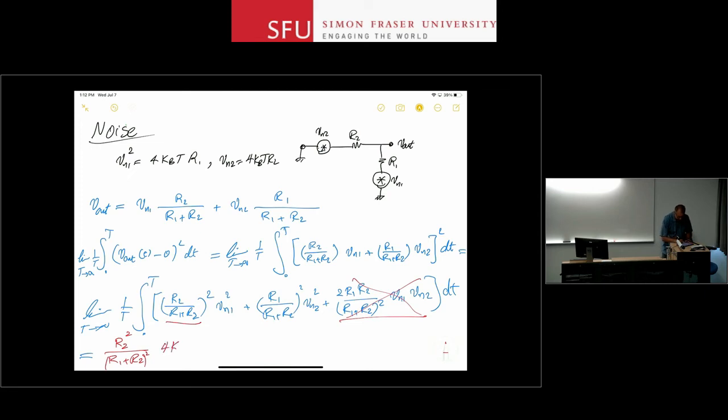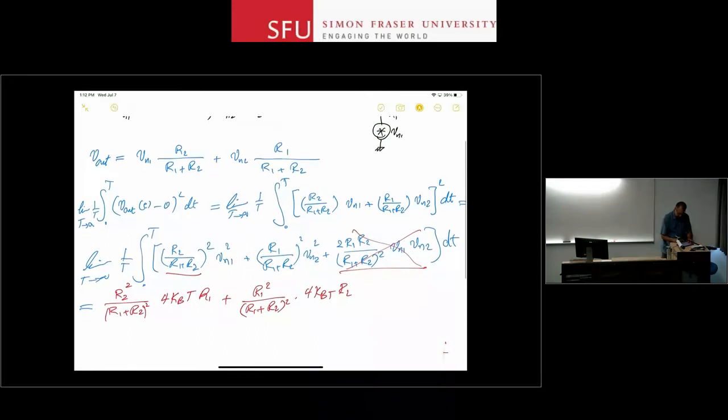It is 4 kBT R1, plus R1 squared over R1 plus R2 squared times 4 kBT R2. Okay? And therefore, I can factor 4 kBT.